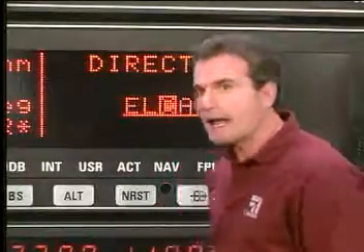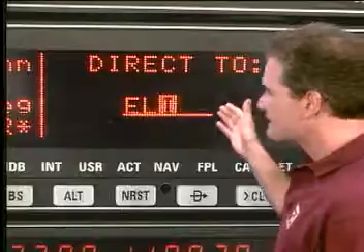But don't ignore the GPS, because you can't find a better tool for position awareness. So what can you do with the GPS? Well, set it on LS-NDB. The NDB is required to shoot the approach, and it is in the database. Not only will you get accurate guidance for transitions and the missed approach, but you'll get distance information too.